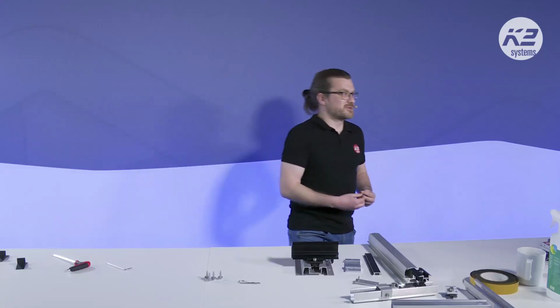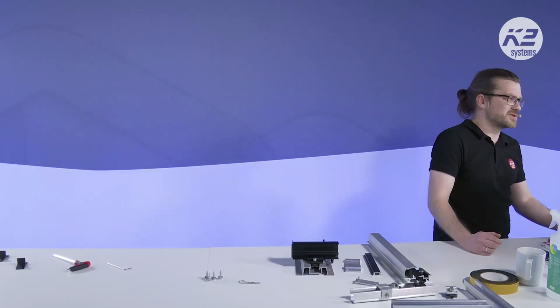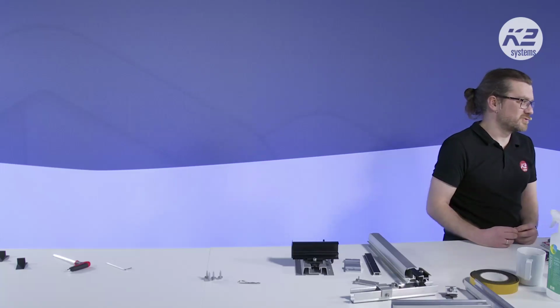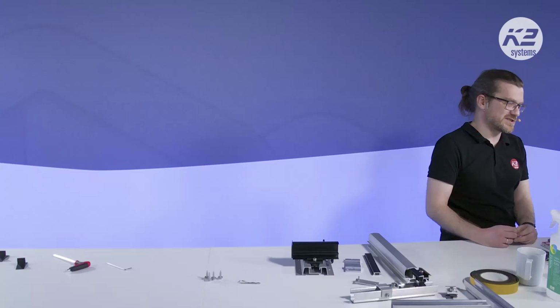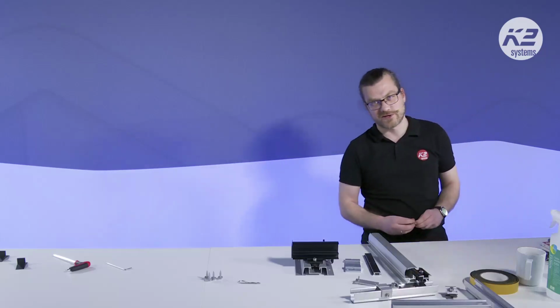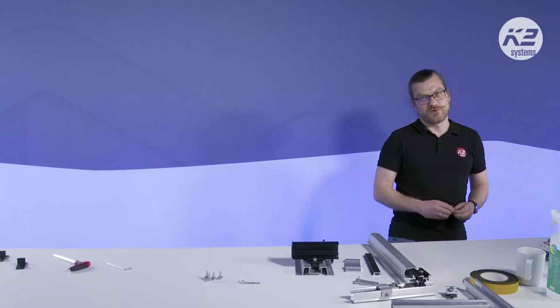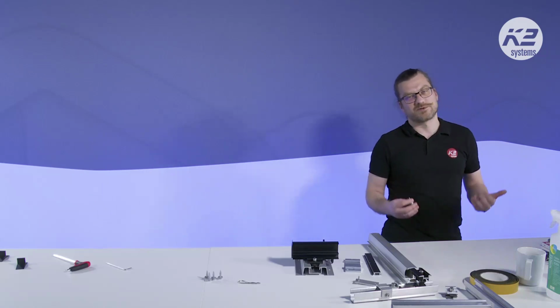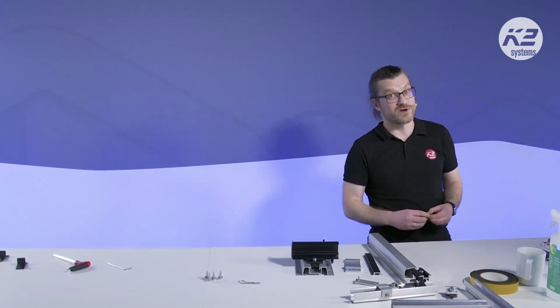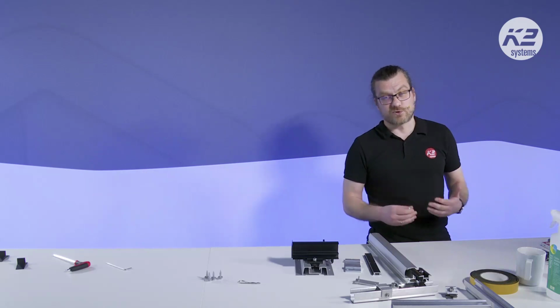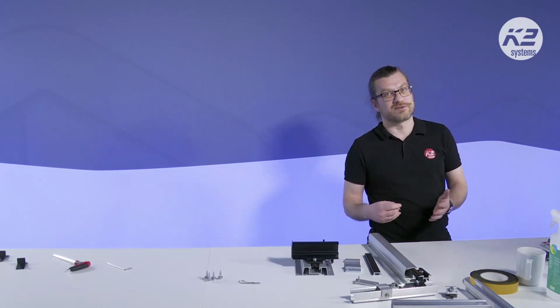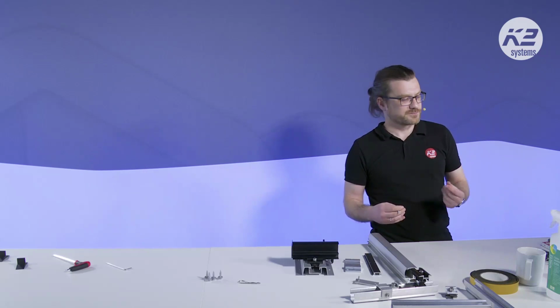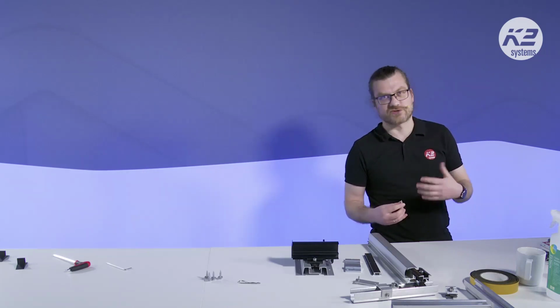Okay, then let me proceed with the written questions. Can we install on a sandwich panel? It's a good question. Yeah, if you have a sandwich panel, you can install our systems on it. But as I said, you will need to check with the sandwich panel manufacturer if they allow it. From our side, our system will hold, but we are not sure if the outer layer is well connected to the insulated structure of the sandwich panel.